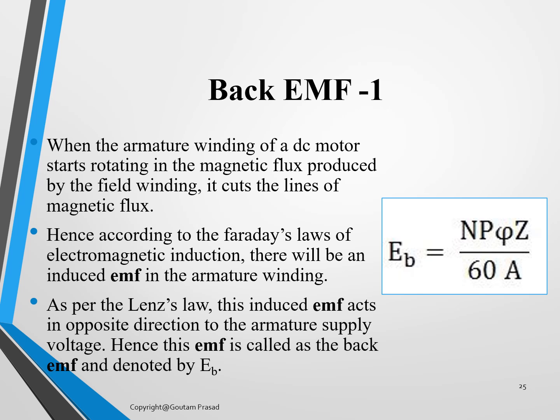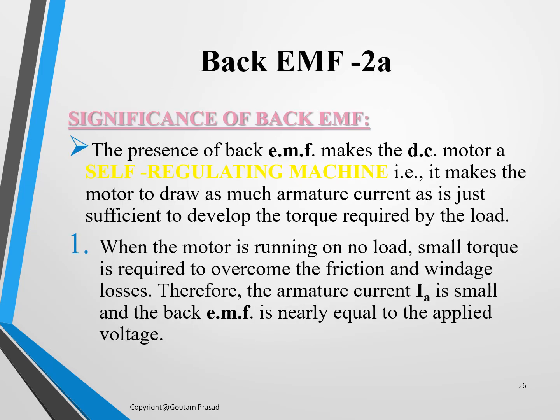And as per Lenz's law, this induced EMF will oppose the very cause that is producing it. So the motion because of which it is being produced, it will start opposing that motion. So there will be a magnetic drag in the conductors. Yet the conductors will have to overcome that force.